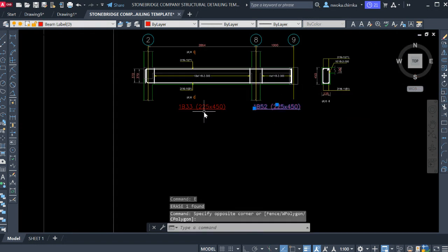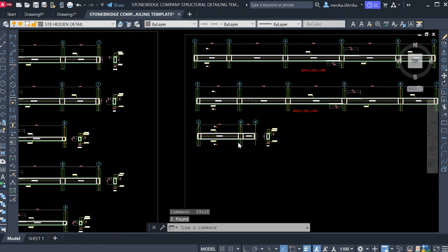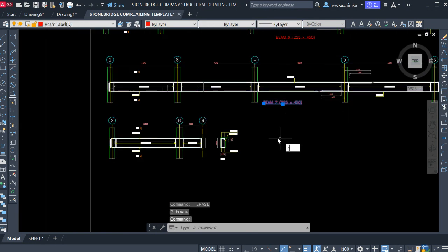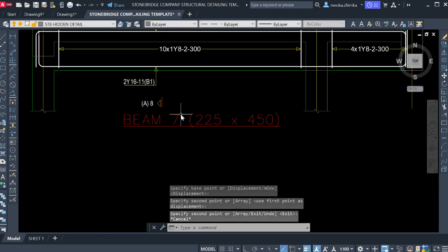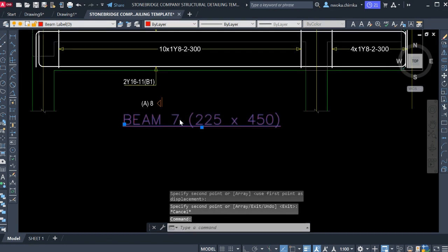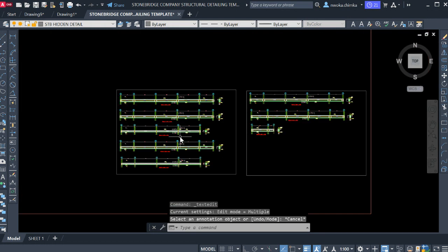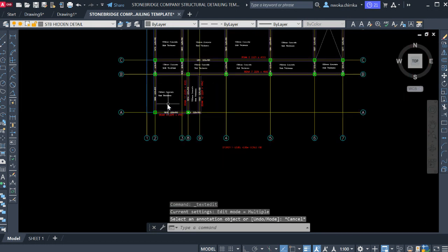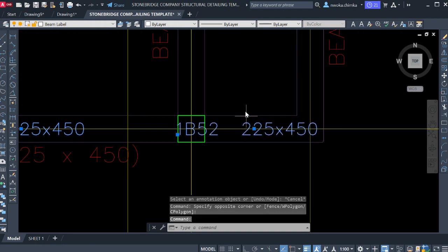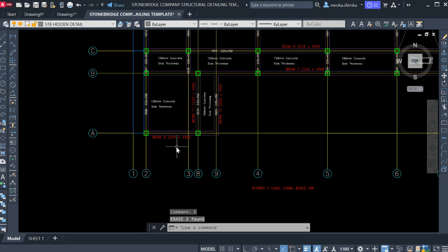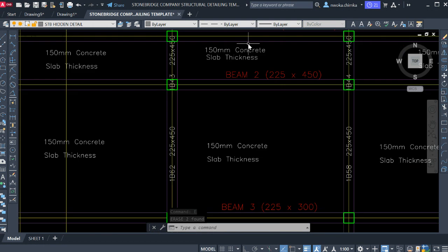Okay, I remove this, and remove this, and then copy this to this place, and then call this beam 8. Okay, beam 8, as you can see it rather than here. Okay, so we can now remove this unnecessary one that came with Prota Structure and just delete it. So we are done with our horizontal beams, as you can see right now.